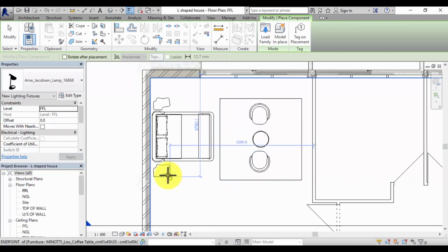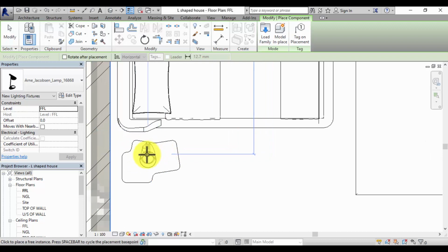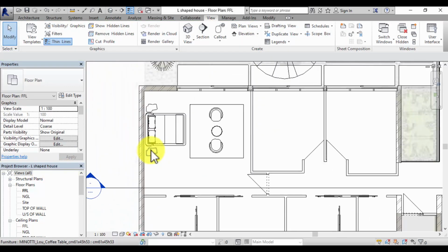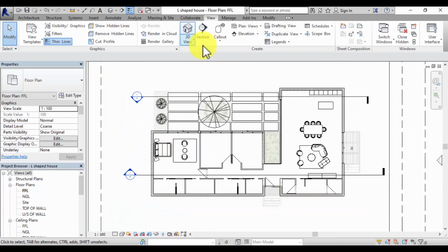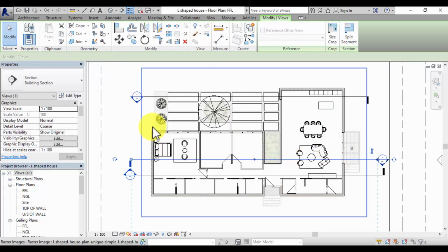and I'm going to do two lights for this exercise. I'm going to put one bedside lamp just to show you how to adjust everything. I'm going to go into my section just to adjust that. If you don't know how to make a section, you make sure you're in the view tab of your model, click on the section line, and you should just be able to draw it up just like that.